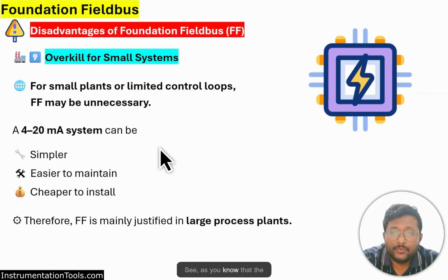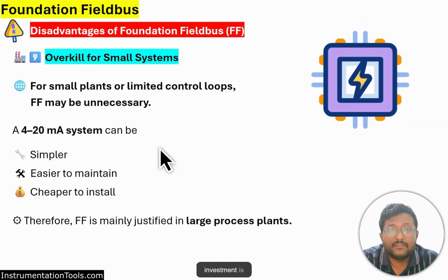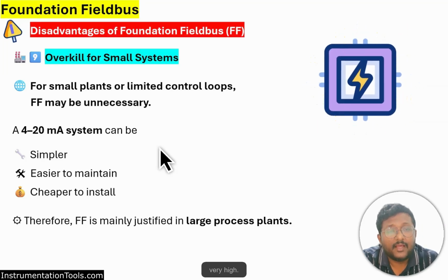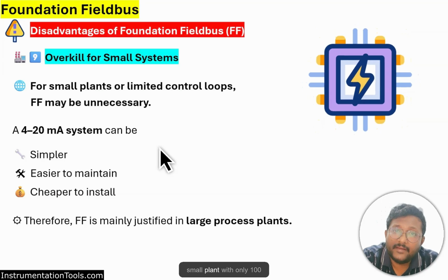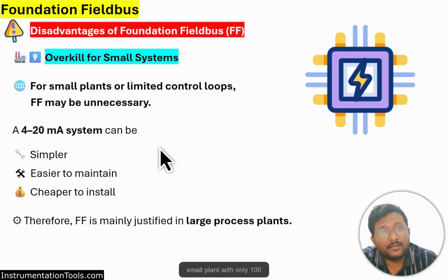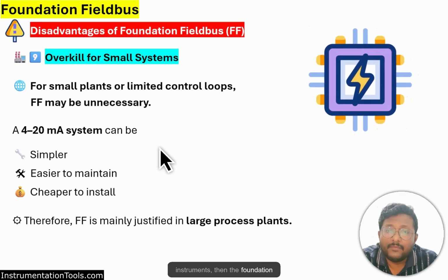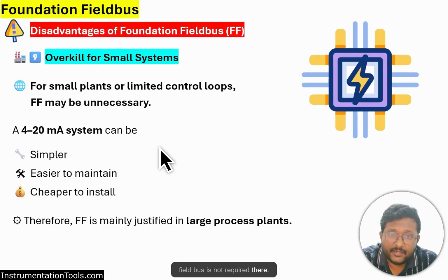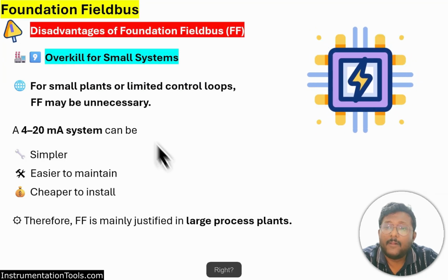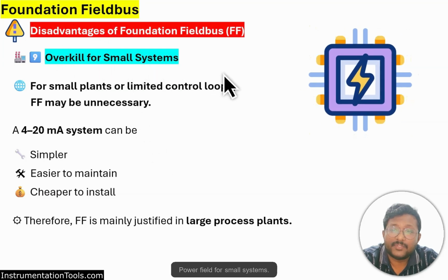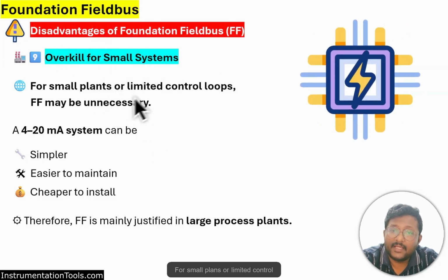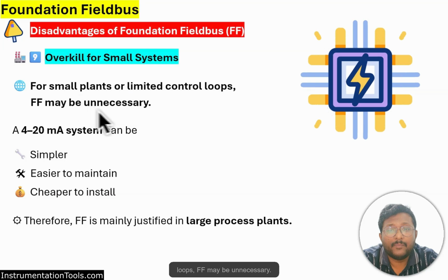See, as you know, the Foundation Fieldbus initial investment is very high. Let us say if you have a small plant with only 100 instruments, then Foundation Fieldbus is not required there, right? Overkill for small systems. For small plants or limited control loops, FF may be unnecessary.